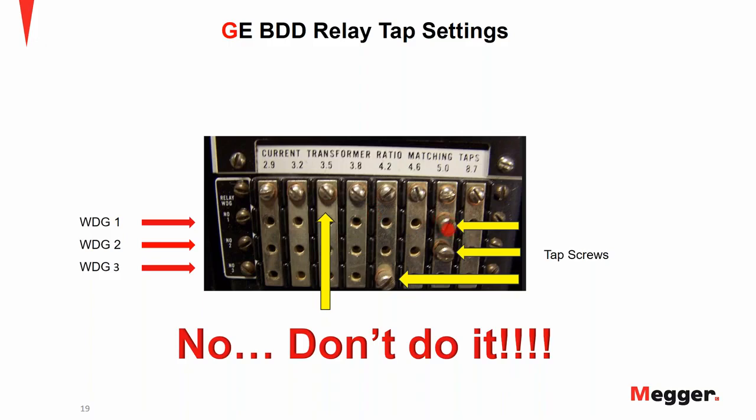These are thumb screws, and they have a little bit bigger head on them so that you can put them in there with your fingers and hand tighten them. If you decide that one day you want to tighten these up a little bit with the inspection that you do on your electromechanical relays, and you twist this guy just a little too much, then he's going to end up breaking this head off. That's a bad day, I'm not going to lie to you. This is when you pull this tap out, put it in this relay, and twist the head off of it, then you need some tools because you're going to be in panic mode at that point trying to get that screw out.